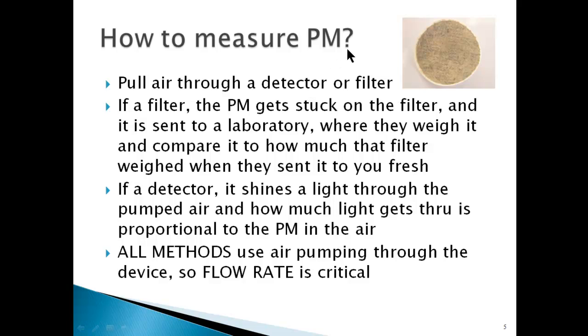Basically, you pull air through a detector or filter. If you're using a device like a Minivol where you place a filter, you put the filter in the detector, you turn on the pump, and it sucks air through the filter, so obviously any particulate matter that's in the air gets stuck on the filter. Then you package it up really carefully, making sure not to shake the stuff off of it, and you ship it to a laboratory where they weigh it and compare it to how much that very filter weighed when they sent it to you fresh.